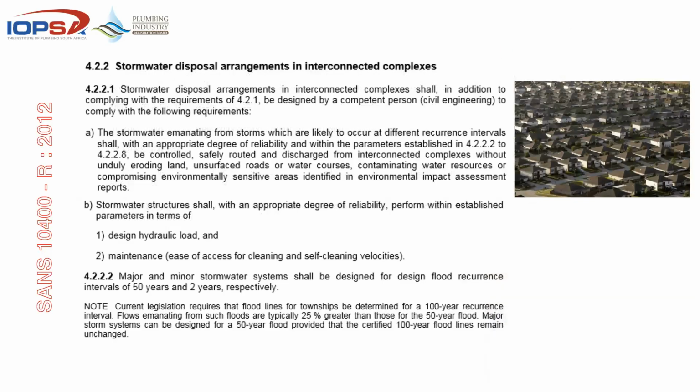Stormwater disposal arrangements in interconnected complexes. Here we're looking at those townhouses, and you'll see firstly it needs to be designed by a competent person, civil engineering. The stormwater emanating from storms which are likely to occur. We're talking about 50-year, 100-year, different types of flood zones. So if you stay in a specific area, if you're in a 50-year flood zone, then in 50 years you would expect to get flooded or expect damage as per records of previous rainfall figures, etc.